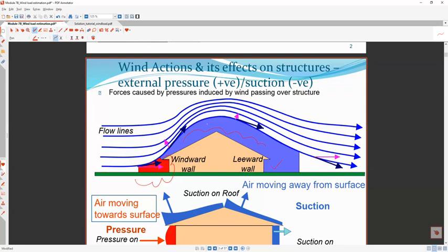That's a separation of the boundary layer. If you have to study that, then you have to study fluid mechanics, the boundary layer theory. Hermann Schlichting has a famous book, which I do have, on how the flow changes in the boundary layer. Here it is pressure because it is directly hitting a surface, and if you apply Bernoulli's equation, we can easily calculate the pressure. Again, that's second fluid mechanics, Bernoulli's equation. Wind or any fluid hitting an obstruction or wall, all this velocity or kinetic energy will be converted to pressure energy, from where you can calculate half rho v square.